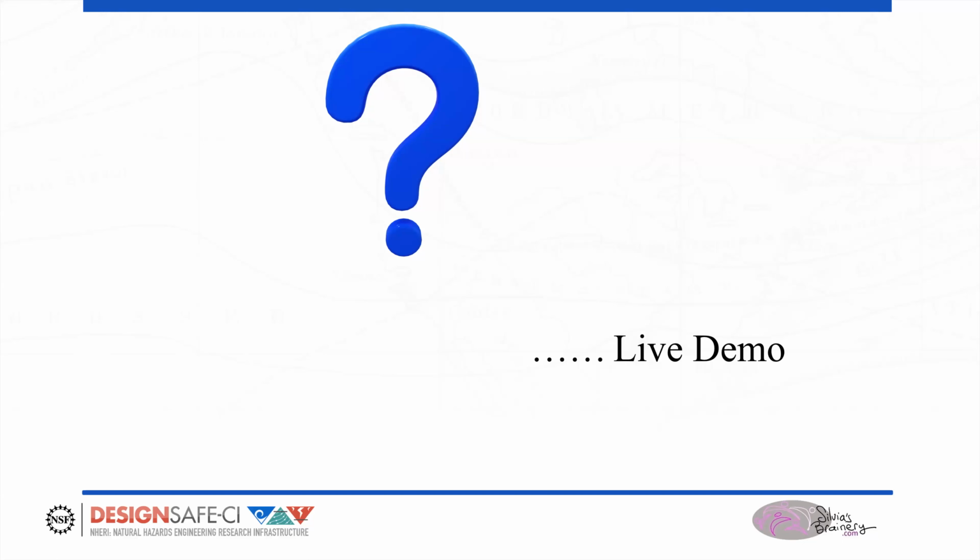Now, if you're running IDAs where you're looking at the results of the previous one, which is what I was talking about earlier as well, then some things need to be run in sequence and some things can be run in parallel. DesignSafe is just giving you the platform to write the script to run it the way you want to. They're providing the hardware. You have to write the script, and comparing it is hard because it depends on whether you have convergence issues and have to iterate, and on the size of your model and other things.